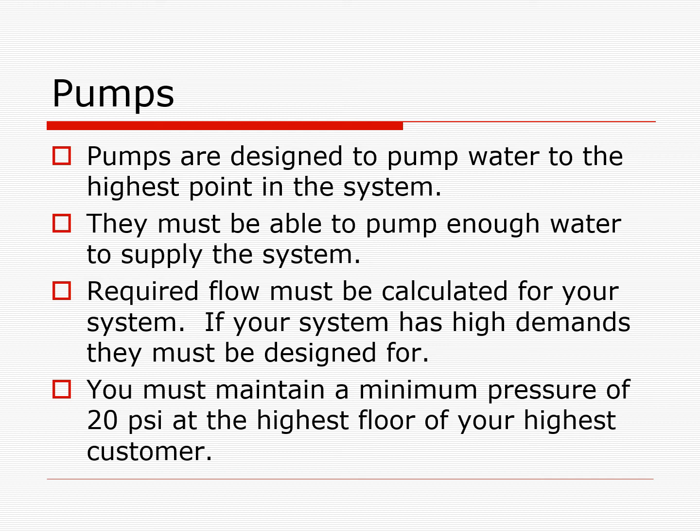Also, health department regulations say that I must maintain a minimum pressure of 20 psi at the highest floor of my highest customer. Because of that, that's maintained in two ways. And if you remember, I said that the water storage tanks also are designed to keep pressure on the system. So they have to be higher than the highest customer by an amount that I could guarantee that my customer gets 20 psi at the highest floor.